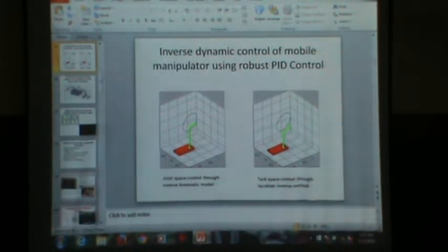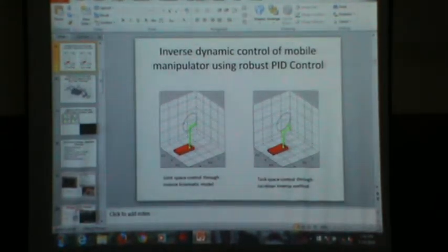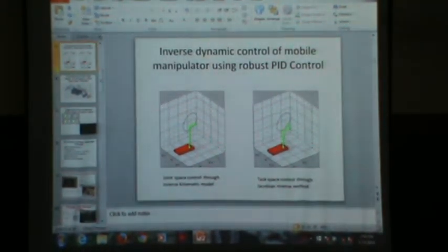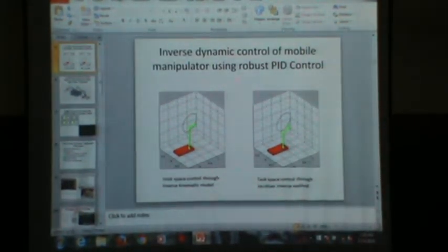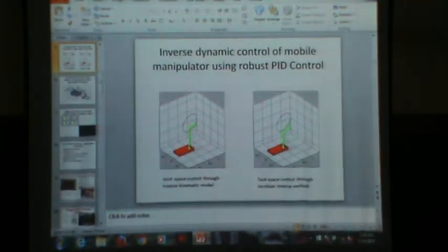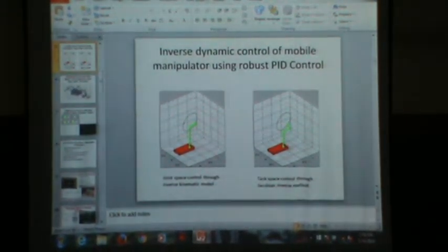Just imagine there is a joint. This joint is a revolute joint. This revolute joint is having a clearance. The clearance is something like this. Okay? This is your pin, and this much I just exaggerated. So this much clearance. Now your calibration model cannot predict where this pin point is touching. So this is the maximum delta error, and based on that only the calibration model will give. But in reality, it may not reach this maximum delta all the time. It may be like this much, or it may be even 0. So at that time, how will you overcome it?